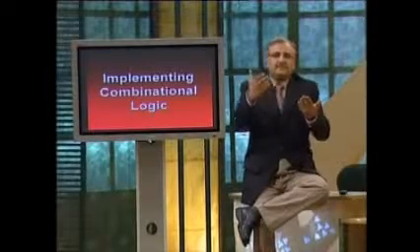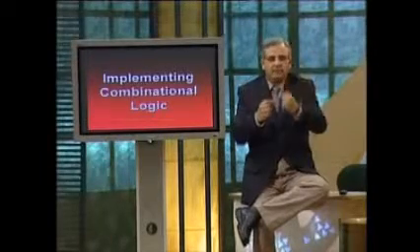You have basically 3 outputs, the 2 sum outputs and the carry output. Now you can directly implement a combinational circuit from the truth table. Now the truth table, remember, has 3 outputs. It would have different combinations of 1s and 0s. Now, to implement, let's say, the carry output, you would select the minterms for which the carry output has been set to 1. So what would be the circuit in terms of sum of product forms?